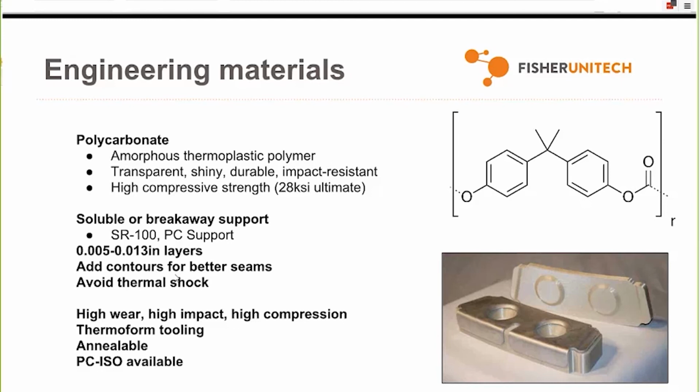So it is an excellent choice for low volume metal forming. And that's an application that most folks aren't aware of. You can use hydroforming, which is the application in this part on the screen, or even smash tooling. You'll get fewer parts before the tool breaks, but if all you need is a dozen or so, it doesn't always make sense to machine it out of steel.